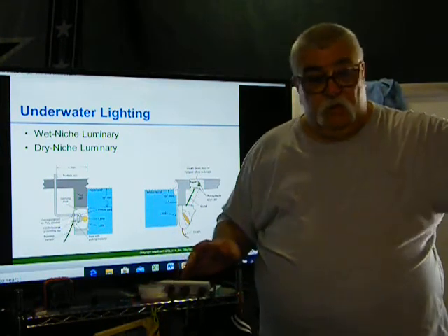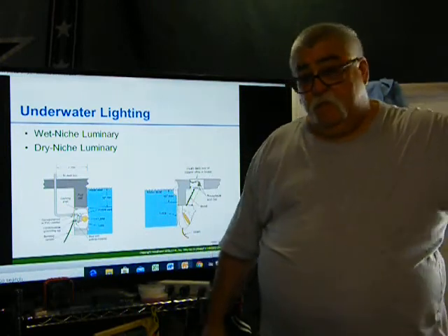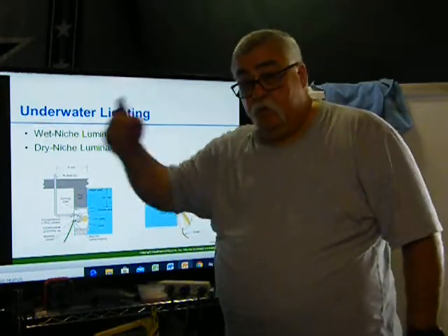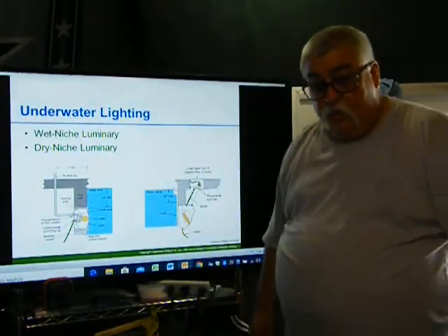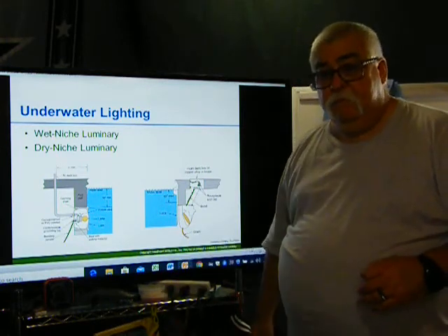So we went wherever the deck was going to be. They said, okay, fine, we're going to have a 10-foot deck. We went outside the 10-foot, and that's where we put the box to feed this luminaire. And then we just pulled the cable to where we were going, because we had to be 18 inches above. They didn't want them in the deck. Why? Because the water level can come up.